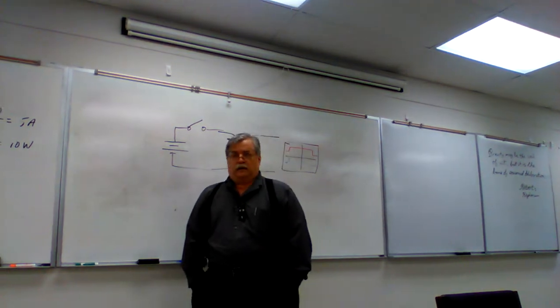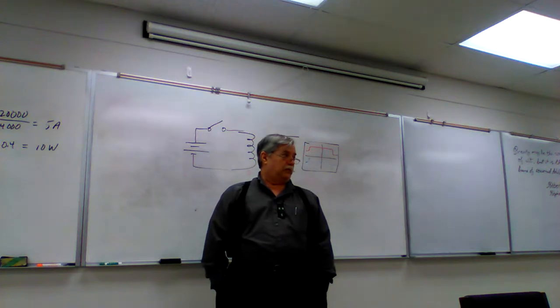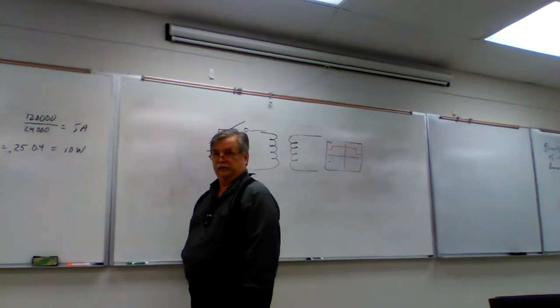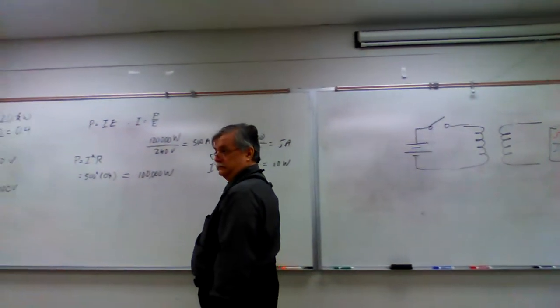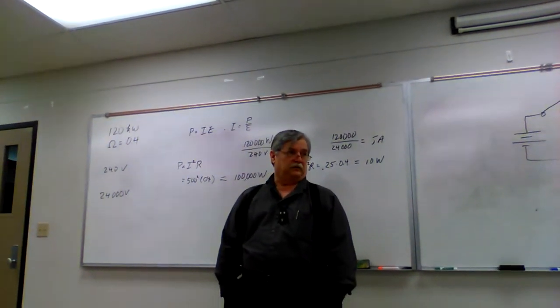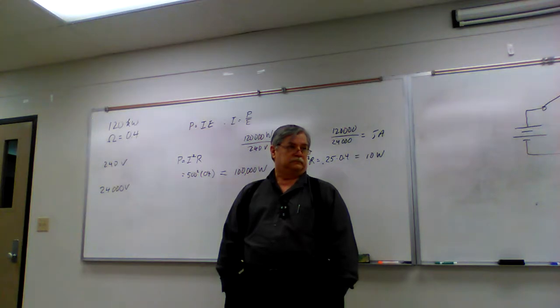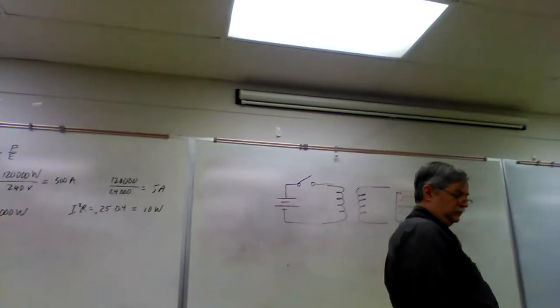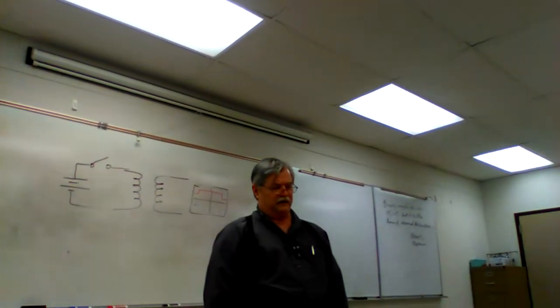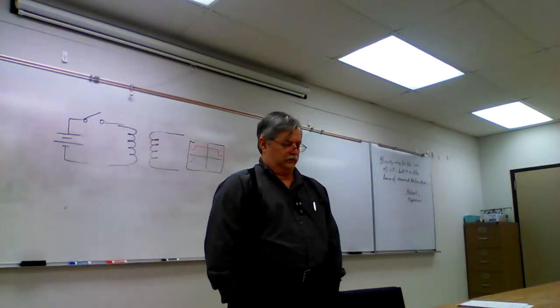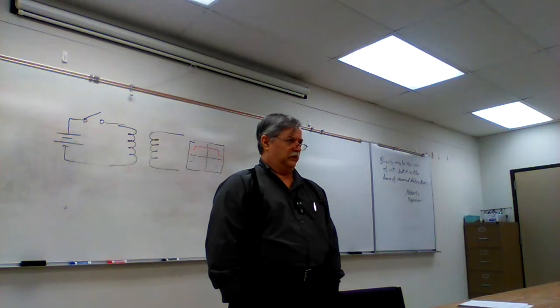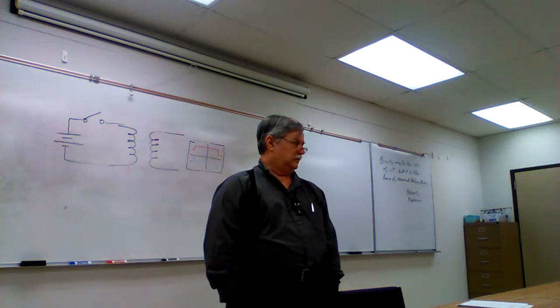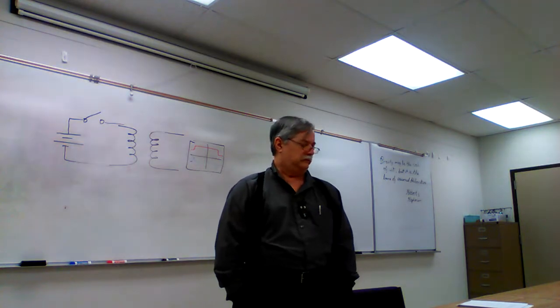So to the extent that you can do so without saturating the core, you want to produce as much magnetic flux as you can. And that means more turns. You're producing more magnetic flux and you're inducing more voltage per amp when you do that.